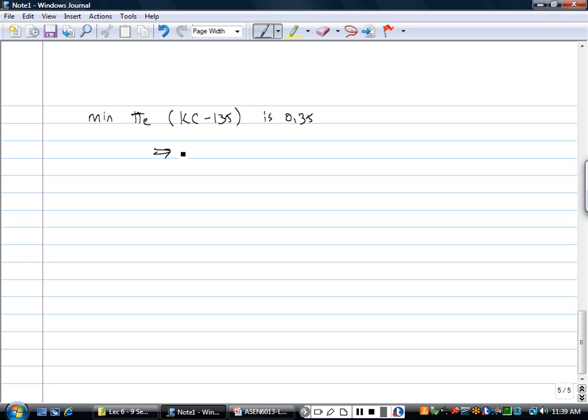So if we look at where this drives, and this is just taking numbers off the curves again, a minimum efficiency for hydrocarbon, if we're way down there, is about 45%, and for hydrogen, as we mentioned, is about 20%. So hydrogen is clearly a winner. It's lowering the weight, it's giving more energy, and it's giving you more favorable numbers in terms of required efficiency. If you follow the literature, hydrogen is always the fuel of choice when you're talking access to space for air breathers.